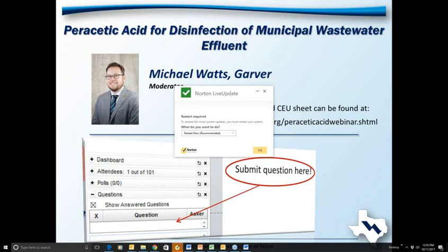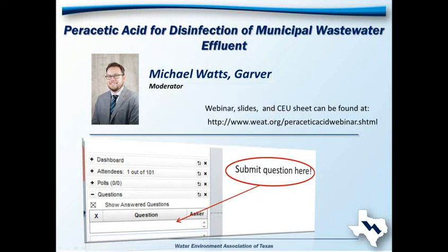We are also getting a couple more questions coming in. Question 4. This is a follow-up, I think, for LRWRA. Are the DPD methods and probes sold, marketed for chlorine? So there's some dedicated probes that are labeled for PAA. The method for measurement is the same as for chlorine, so you can use chlorine probes as well and use correction factors for PAA. But again, there are probes specifically labeled for PAA, so that correction factor is already factored in. And then the DPD kits, there are some on the market from WRRF that are specifically marketed for PAA, so those are available.